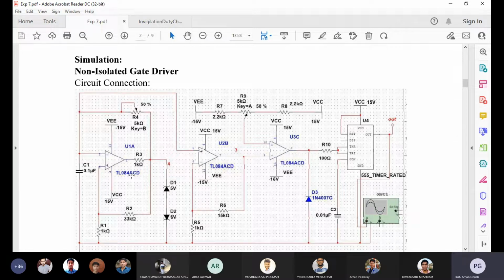One is positive bias voltage, that is positive VCC, and another is negative bias voltage, that is negative VCC. So a total of 14 pins. If there is any ground terminal beyond that, you can cross-check it, depending on the number of terminals required. The selection of the op amp is also decided by the maximum kilohertz range it can run, otherwise it will not work.